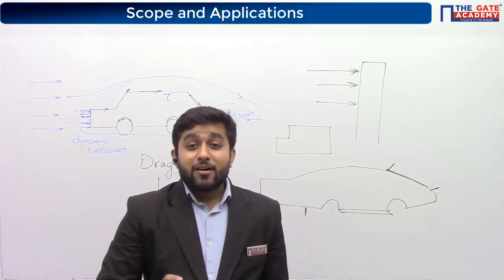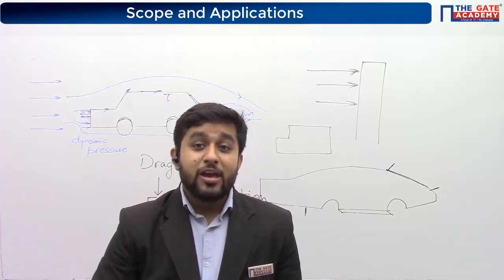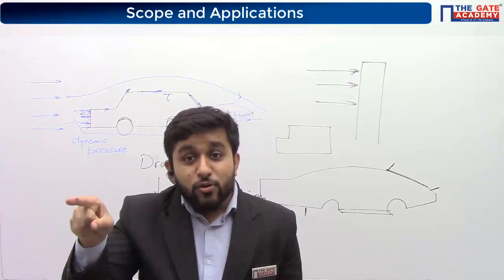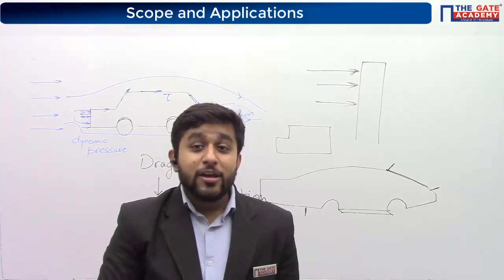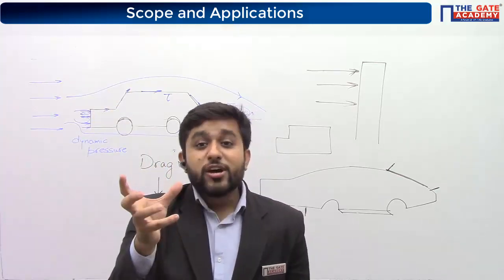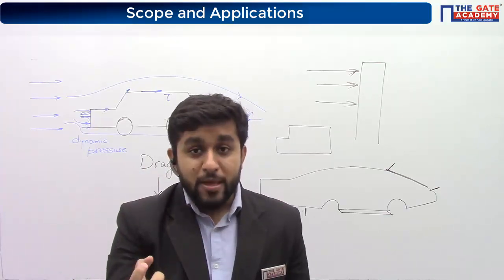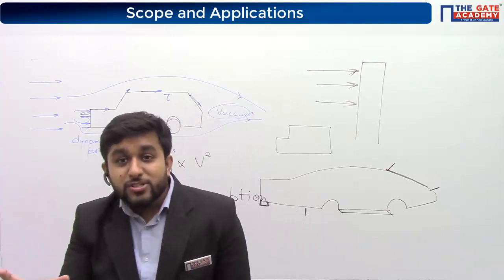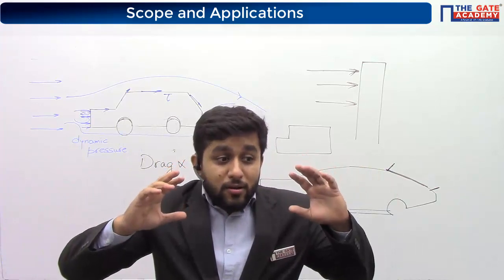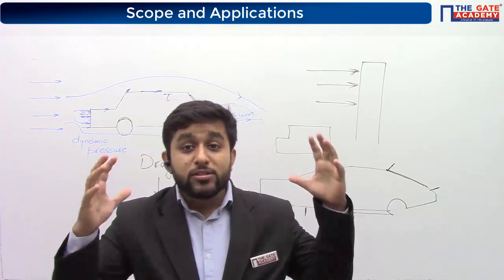So actually, not only the outer body, but in fact the engine is very much based on fluid mechanics. First of all, the air will come inside, it will pass through the air filter. From the air filter, it will go into the air intake manifold. In the air intake manifold, the petrol or CNG will be injected. Now the mixture, so basically the flow should be turbulent so that the mixture formation is uniform. Now this mixture moves into the combustion chamber where the burning happens. So to allow the proper amount of fuel going inside the combustion chamber, this flow should be proper.